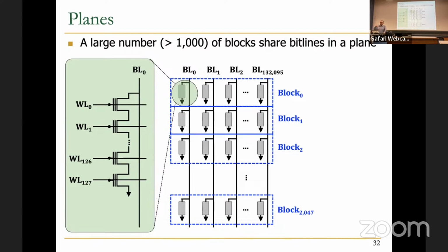No, but that's the operation for the write buffer, essentially. For the write buffer, no matter if it is DRAM or SLC, you need to first write to that in order to have 4 pages. So you write to that SLC, and then whenever you have 4 pages ready, then you write. So that's the process. We're going to get back to that when we discuss fine-grained mapping.